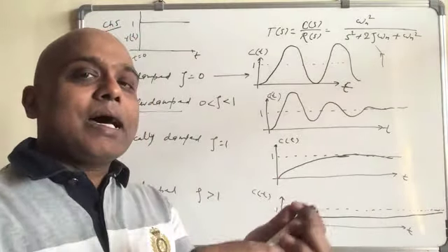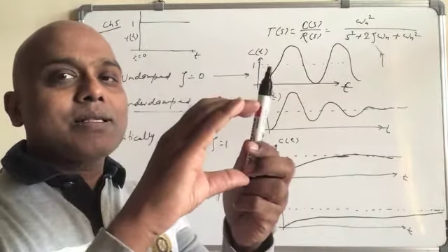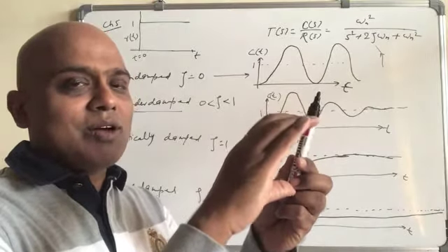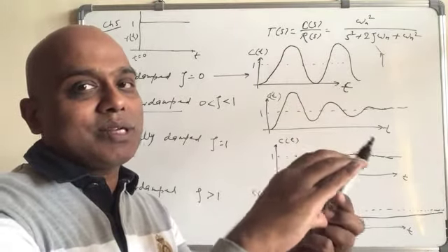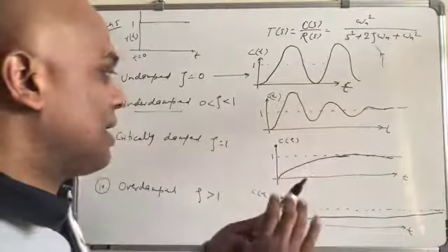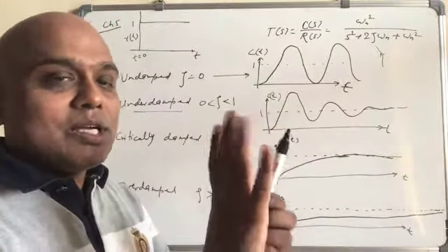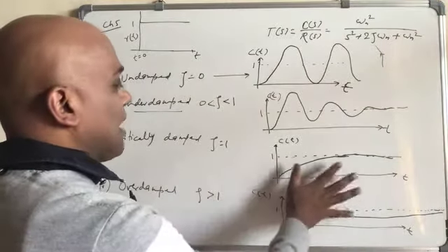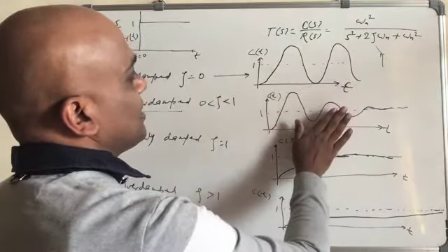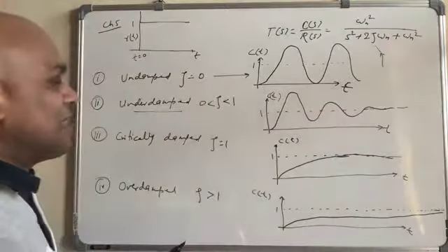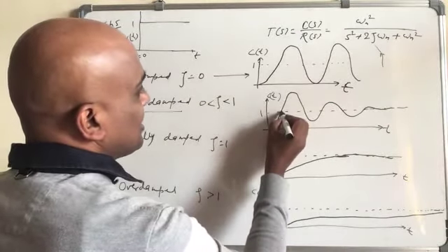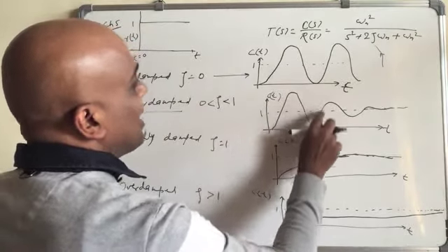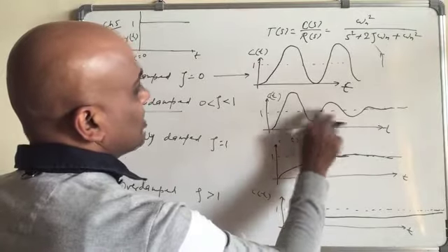And then let us say the spring depresses, and it takes a long time to go back. So it's not a good idea, because in the meantime there may be some other pothole also, and that time it will not work. So you want a fast response time. In that case, instead of having overdamped or critically damped, you want something in between where the response is very fast. What you see here, from here it goes here, but you can choose zeta such that it is even faster. You can settle very soon also.